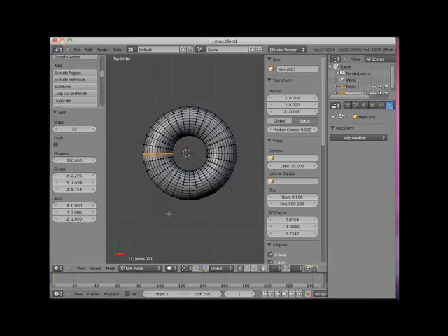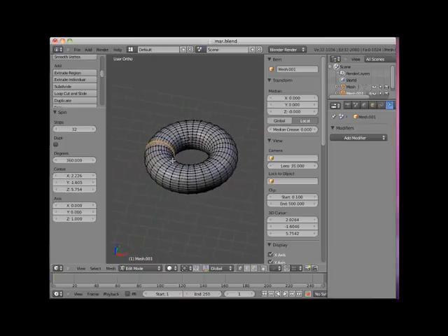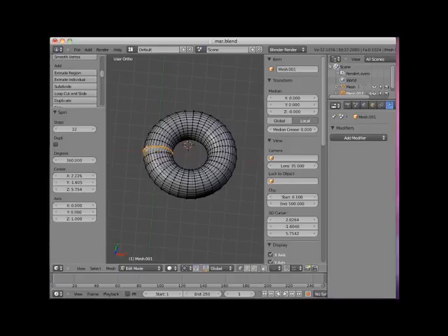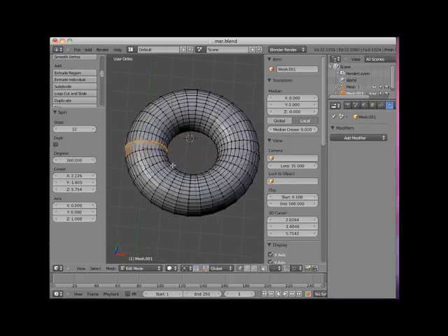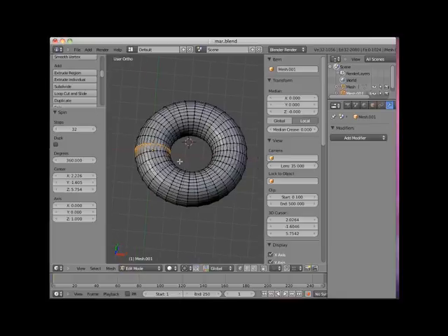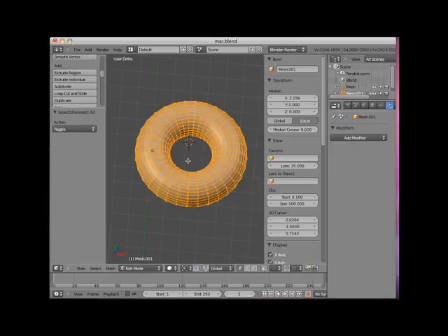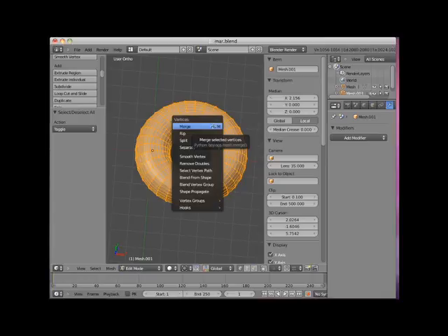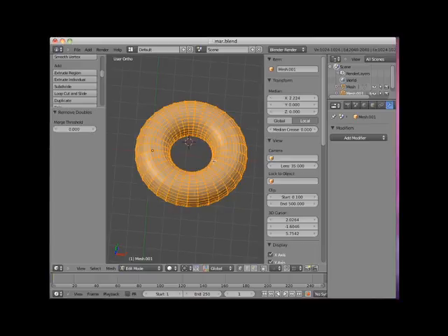If we spin an object selection 360 degrees, it means that the last extrusion segment is placed on top of the original selection set. Now we can remove these duplicate vertices by first selecting all of the vertices. And by the way, note on the information editor header that this object has 1056 vertices and all of them are selected. Then press Ctrl V, which displays the vertex menu, and select Remove Doubles. Note now that there are only 1024 vertices in this object.